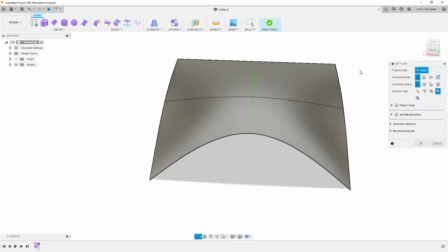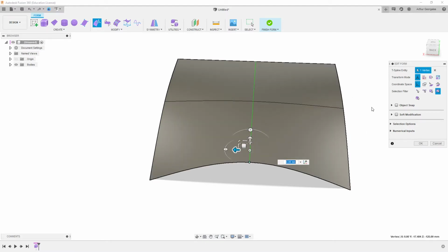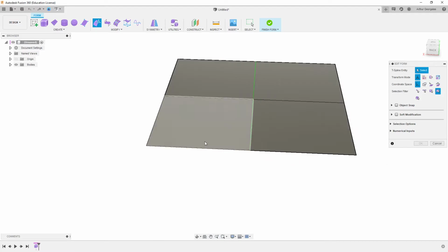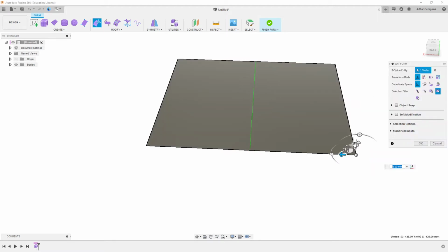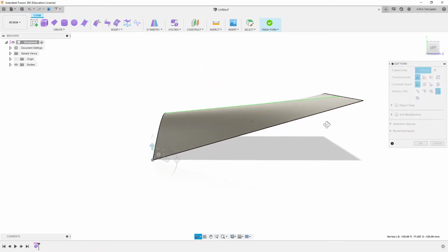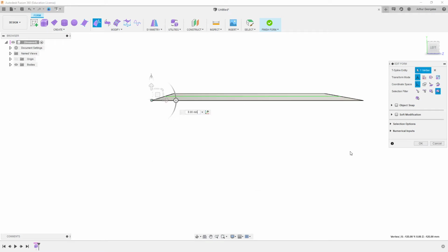But we do want to be careful that we don't overcomplicate our geometry. So what I mean by that is we currently have 4 faces, right? We can actually go in and remove faces. So if we get rid of that, now we don't have a separate dividing line in the middle that we can edit. So when we pull that down, it edits from all the way across as opposed to going from halfway and curving it.